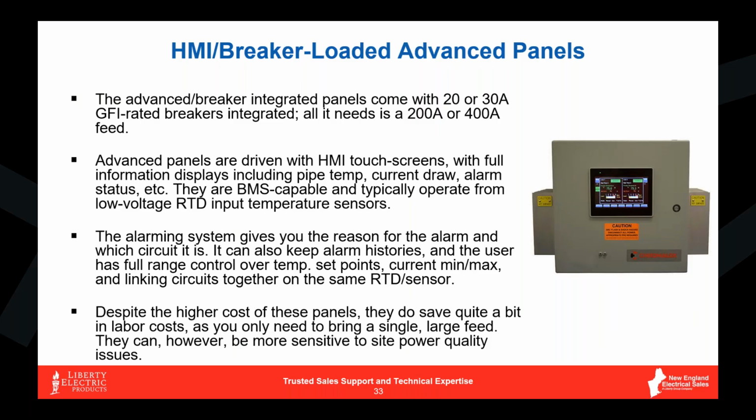When we look at these advanced loaded HMI breaker loaded panels, sure, nobody loves seeing that price tag in the bottom right-hand corner. I get that. However, this panel is also saving you a tremendous amount of labor time. Because again, instead of having to wire over each one of these 30 amp breakers to a circuit in that contactor relay panel, I just have to bring one big honking feed into this guy, and it distributes all that power internally. So it's a much less time consuming install generally versus contactor relays.